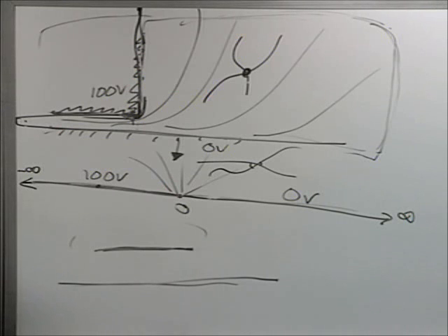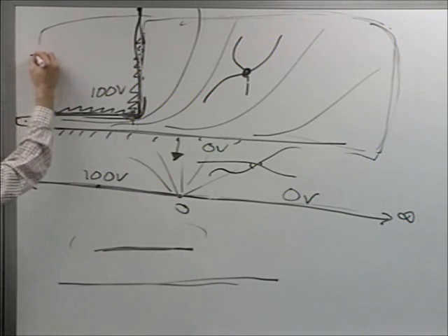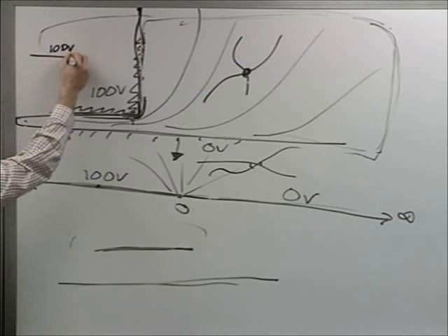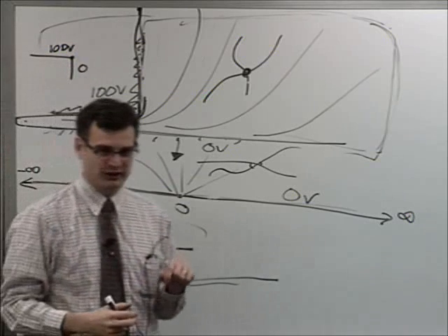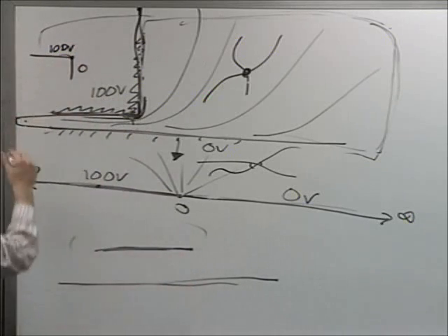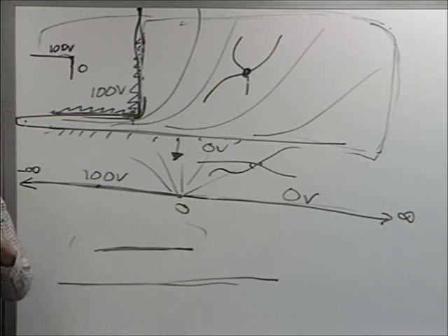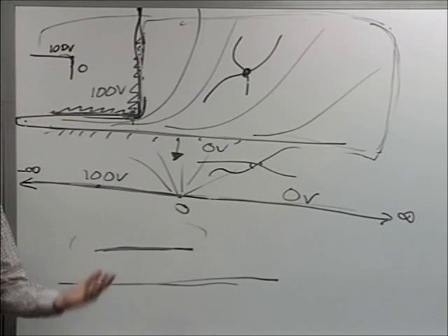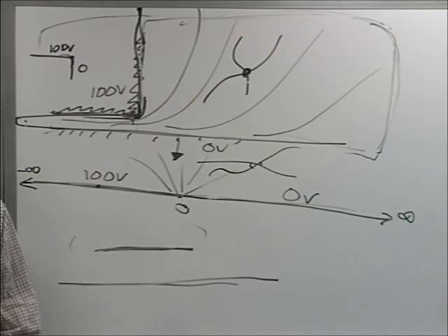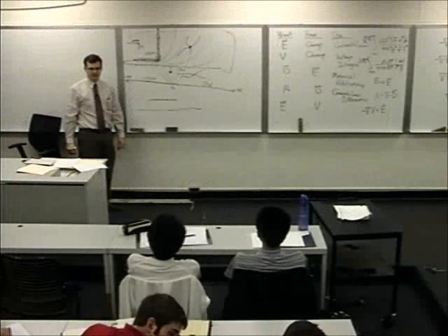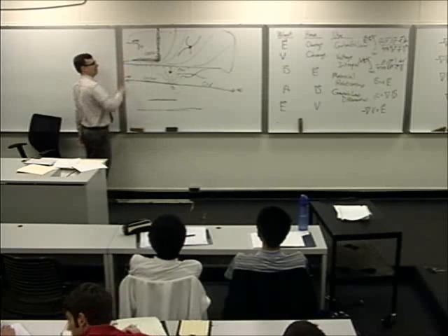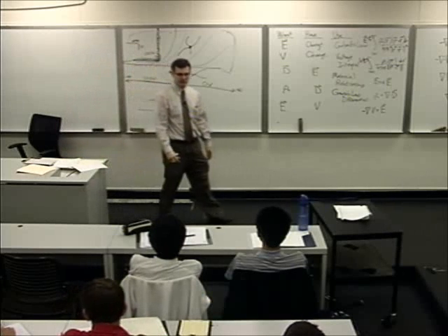But in a lot of these types of problems where you have a plate at 100 volts and then another plate at 0 volts, there's an assumed little dielectric bead or something keeping current from flowing from there to there. So it can look a little bit fishy to an electrical engineer who's used to circuit analysis. Say, wait a second, I've got a 100 volt drop across 0 distance in space. I've got infinite field right there. That's no good. It's going to end in a fiery arc. But, well, you put a little bit of gap there just to keep it honest, physically speaking.